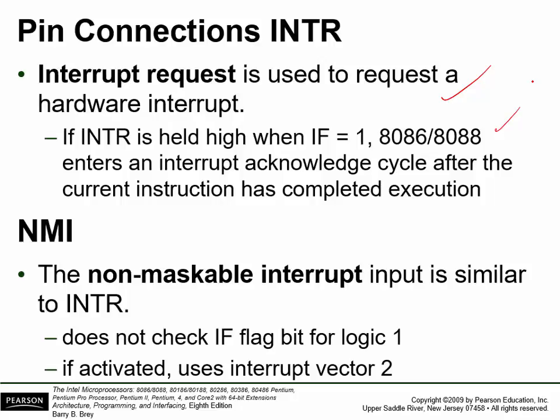With the 8086, there's one pin called the interrupt request, in which case, when that happens, an interrupt has occurred, and the microprocessor would go out and ask the interrupt controller what interrupt occurred. With the 8051, which is what we'll look at in more detail, the pin itself will tell us what interrupt it is. But we would then go and service the interrupt.